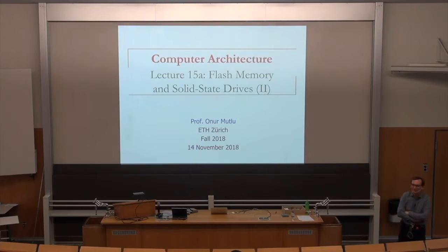I'll give you an example that's more or less public. Basically, wear leveling. These emerging technologies have an endurance problem similar to flash, so they all need to do wear leveling internally. Some of the techniques inspired by flash are used for PCM SSDs, for example. But of course, they're a little bit more efficient and slightly different.